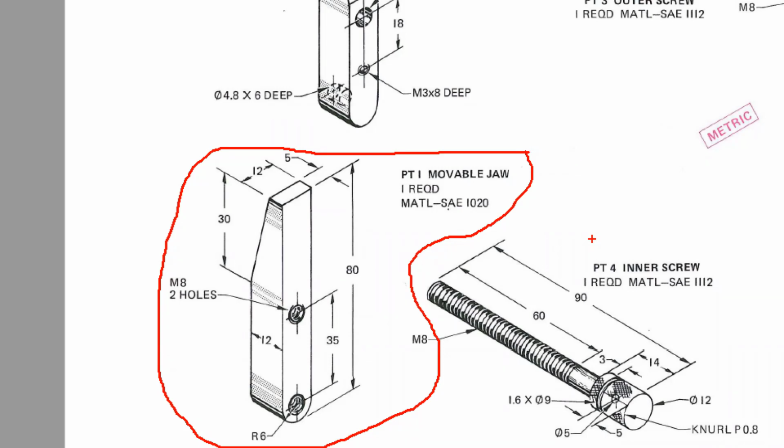What is the pitch? Whatever the biggest one is, right? If you're putting that note in your drawing, it can just be M8. If you're doing it in AutoCAD, you can just put M8. If you're doing it in Inventor, you'll pick M8 in the largest thread and it'll come in right. So this is a pretty simple part. Make the orthographic views for the drawing of that part.